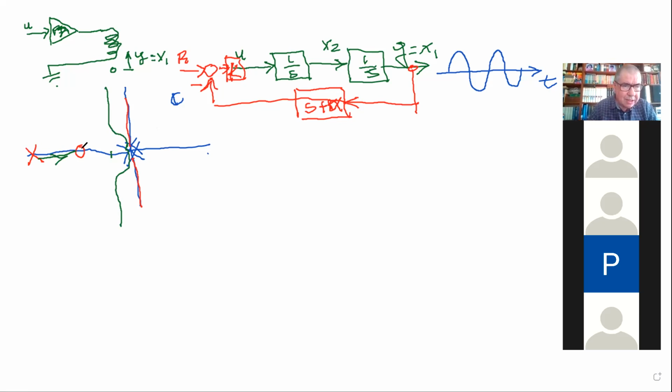So this 0 attracts. Okay, so in this case, this will be S plus alpha over S plus beta, with beta bigger than alpha. Now, okay, this is one possibility. I could have placed this stuff there also. In terms of the root locus, it would be the same. Do you know what is the difference of placing this stuff here or there in series with K?